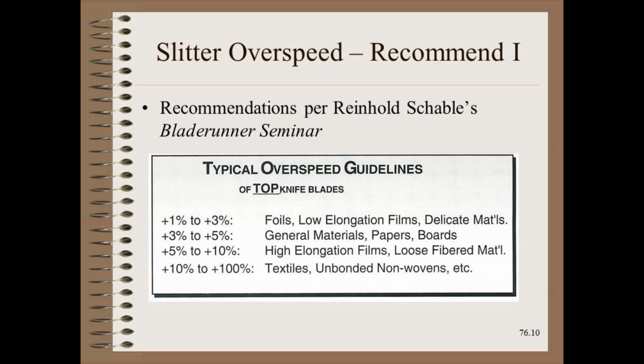The previous theoretical considerations are merely a starting point. Experience is even more valuable a teacher. Here, experience has shown that overspeed should be in the 1 to 100% range, depending on the web material to be cut. That, to put it mildly, is quite a range.